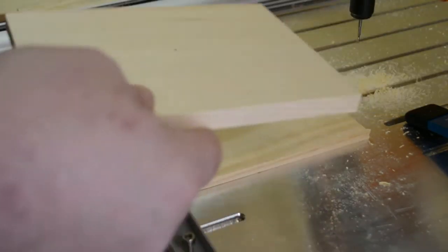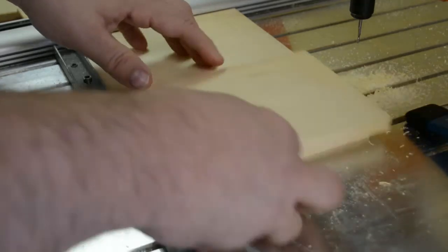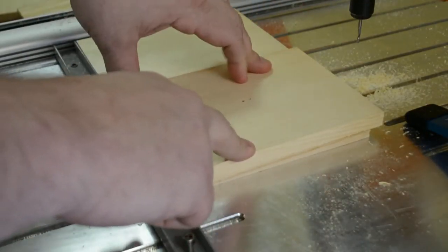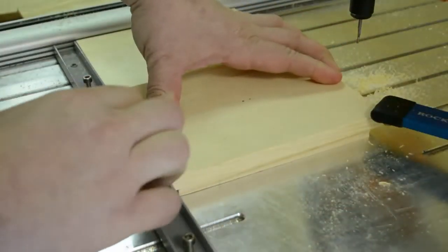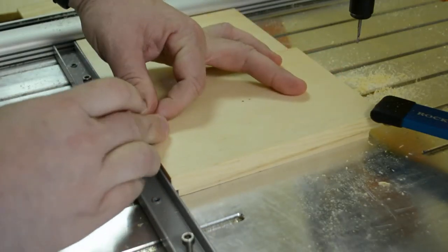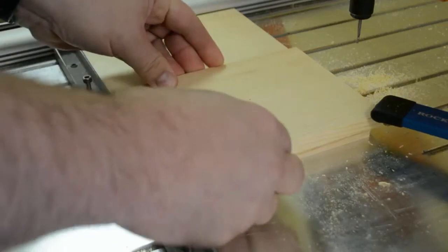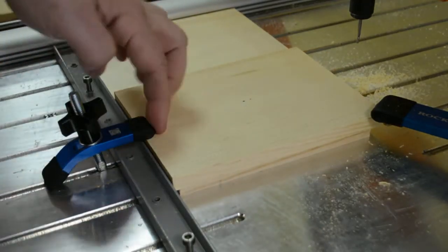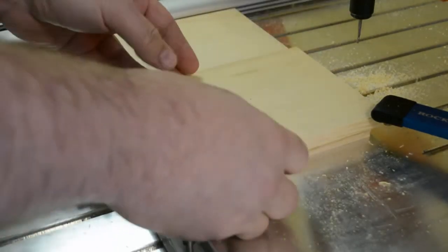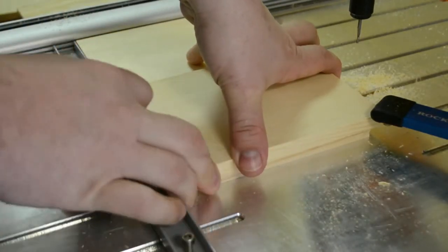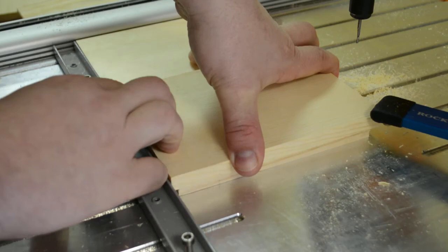So this way, when I'm doing multiple Scrabble tiles, I could just put it in, line it up against here and the edge, clamp it down, and we're good to go. Now all I have to do is rerun the file, and I don't have to worry about re-zeroing the workpiece. So that piece is in there, it's all set to be cut. And when I'm done, I can just take this one off and put the next piece in, and I will show you that as soon as this one is cut.